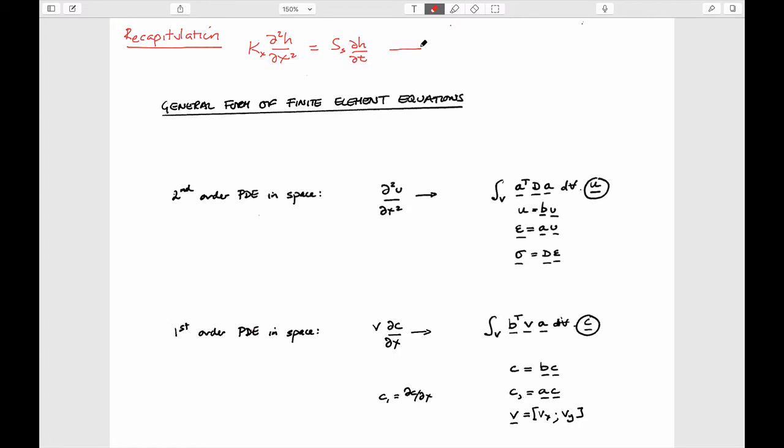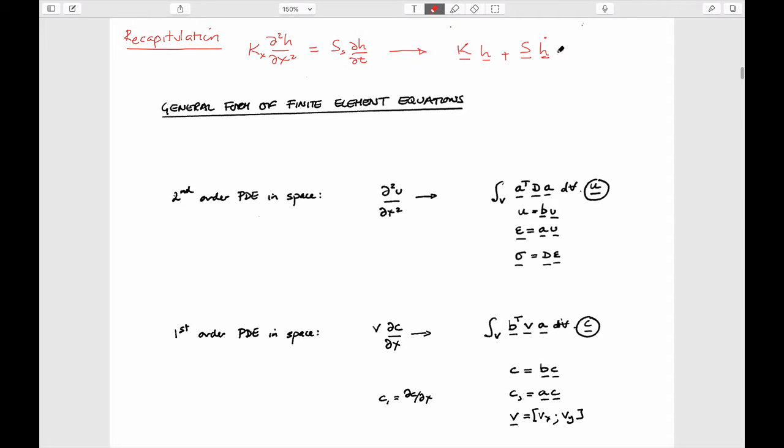We've said that we can take that, and we spent a large part of last time we met taking this and rewriting it as an algebraic equation, which had the same dependent variable locked into it. And we looked at what these individual matrices might look like. These would be magnitudes of nodal heads that describe the system. These are rates of change of those heads, defined only at nodes.